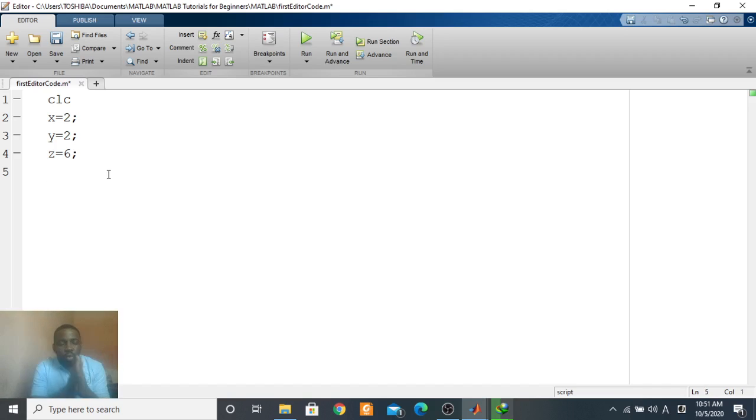Many times this is what we need. You can echo your answer on the command window if you want to see the result of a particular variable without having to use fprintf or disp and the like, but clean code requires that you always put a semicolon at the end of every line of execution.